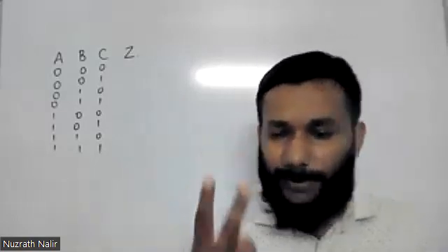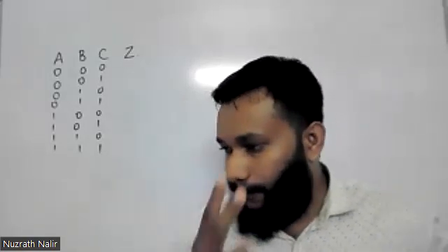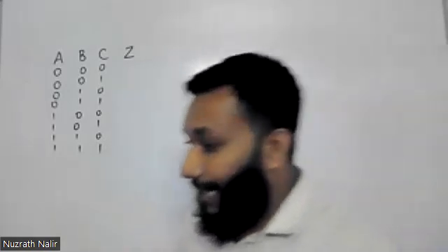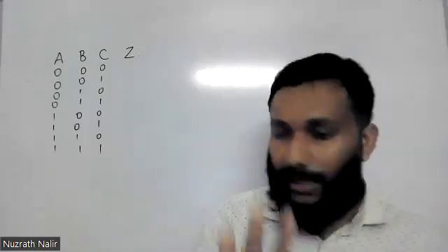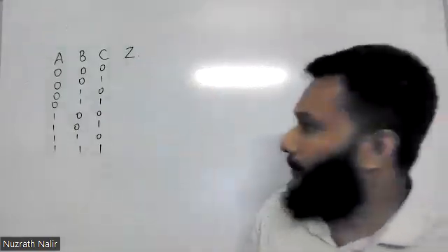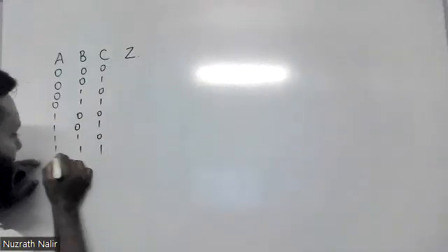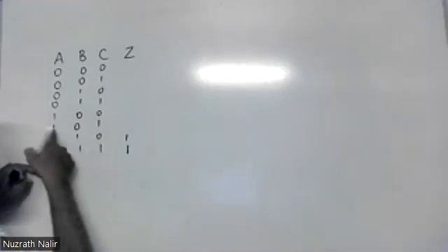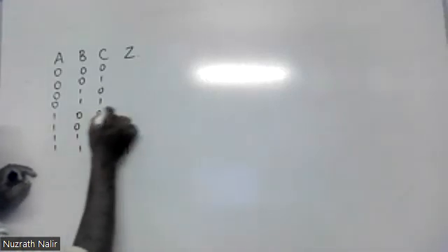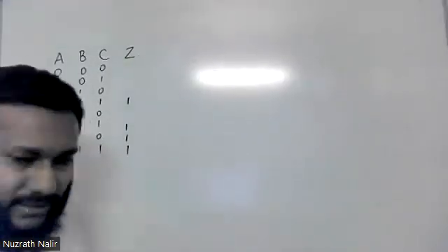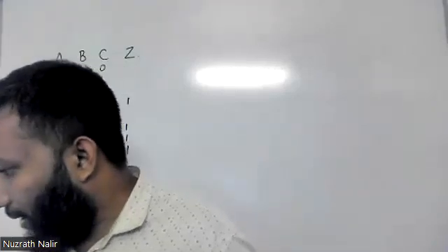If at least 2 of the inputs are 1, you can take the output as 1. At least means not only 2; the minimum is 2, and the maximum 3 is also possible. So directly here this is 1, and for this, 1. For this, you can write 1, and for this, 1. The rest are 0. Otherwise, the output is 0.